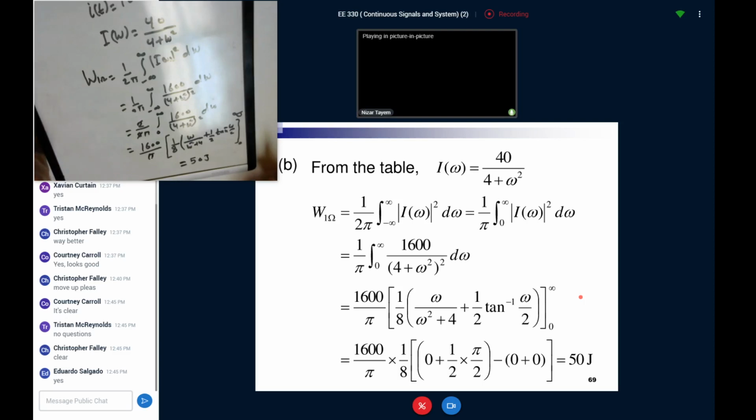But if you need to find the essential bandwidth to send a certain signal, then you must use the frequency domain. Normally we use the time domain to find the energy of the signal, and then we can use the energy of the signal and substitute that in the frequency domain to find out what the required bandwidth is. This is in general. Again, the process is complicated and the integral is more complicated compared to the time domain.